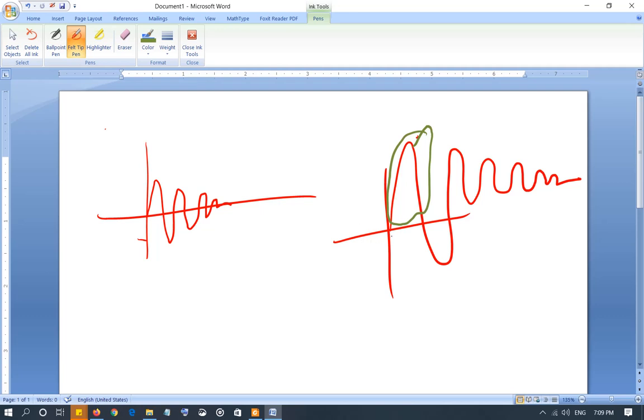So the idea is to create an underdamped circuit such that when we activate the switch, it is going to create a sinusoidally exponential waveform, and as soon as it hits zero, up to this point, we turn the switch off, and then we turn the other switch on, which will let the same waveform go in the opposite direction. So that's the basic idea of resonant pulse inverters.